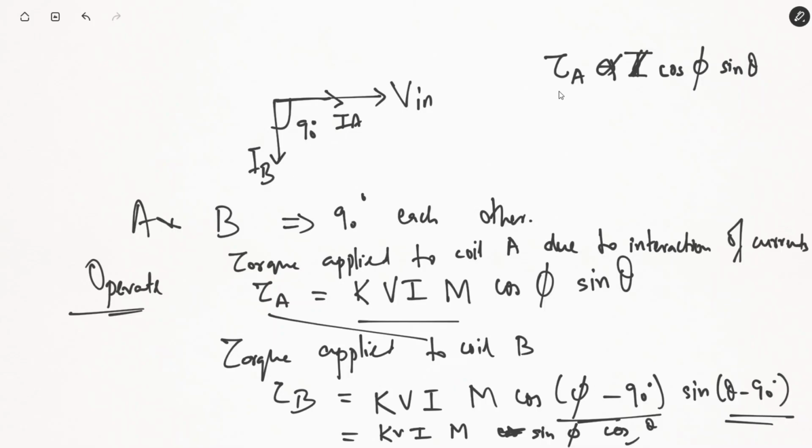Right? You have two voltage coils. You have a voltage coil divided into two parallel paths. One parallel path is purely resistive, another parallel path is purely inductive. So the currents in the two coils will have an electrical angle of 90 degrees. We also place these two coils mechanically at 90 degrees to each other. Now the current is flowing through the current coil as well as the pressure coil. It's AC current flowing through these, so a magnetic field will be produced.